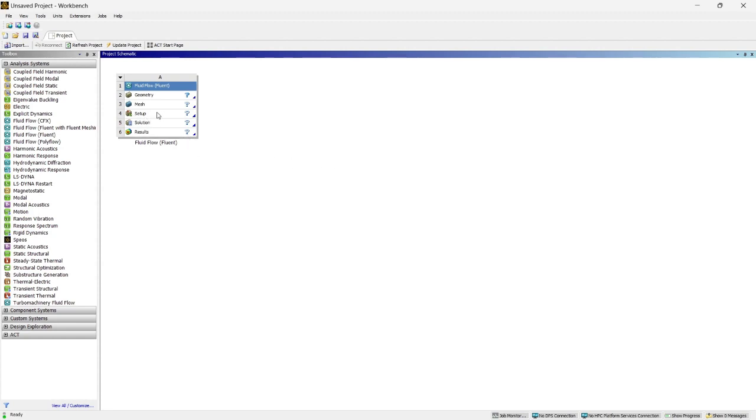In the setup part, you will be giving the boundary conditions, applying the various parameters like laminar flow, the density of the fluid, properties, the material which you are dealing with, all those things. And later on, you will be running the calculations and initializing to get the solution and further the results.